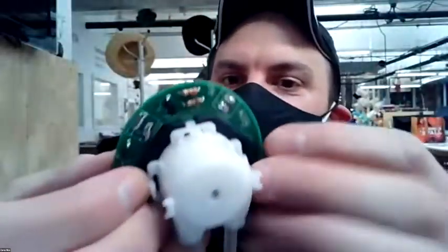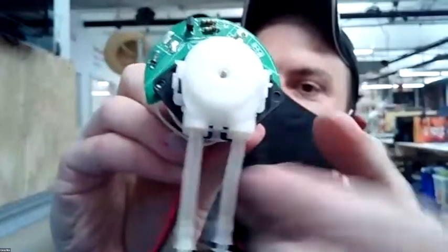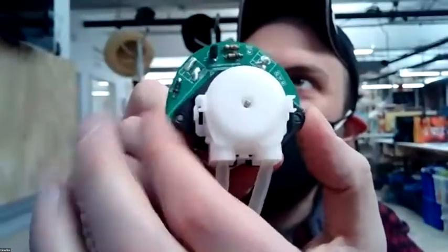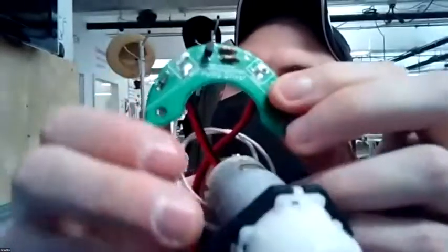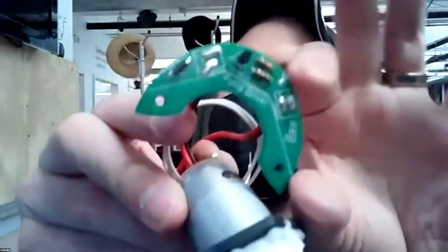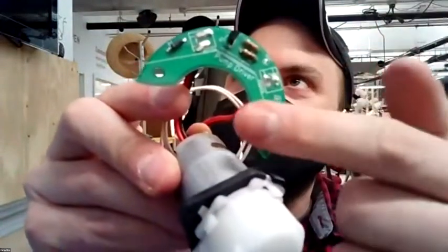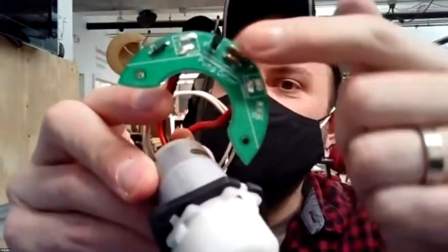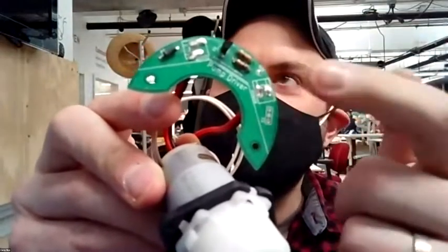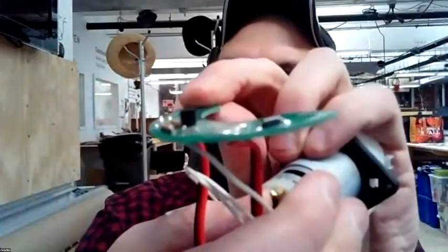So I used Fusion 360 to collect in the geometry of this pump mount, this like black piece right here, and then used it to design the shape of this circuit board to fit around that motor to not extrude too far out there. I drew in this line where that mount ended, and then I could put in just a couple of through-hole components. This is a totally through-hole board with no surface mount on it that I ordered custom made.